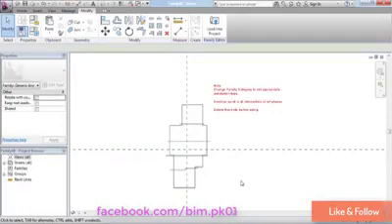Now again, if you had created that geometry directly in the view, Revit would have generated an error message saying you can't paste between project and family. So that's why we did it that way. That's why we drew the stuff in the sheet view first.